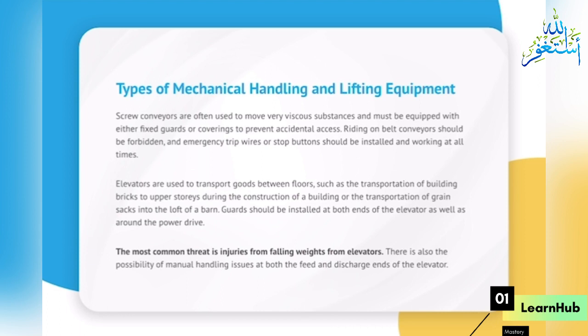Guards should be installed at both ends of the elevator as well as around the power drive. The most common threat is injuries from falling weights from elevators. There is also the possibility of manual handling issues at both the feed and discharge ends of the elevator.